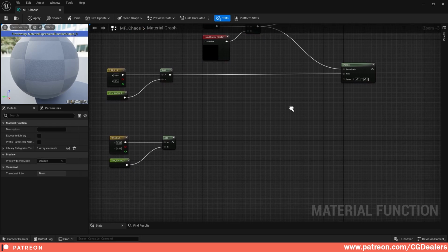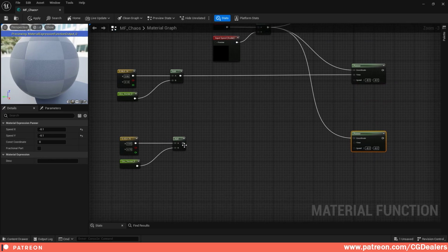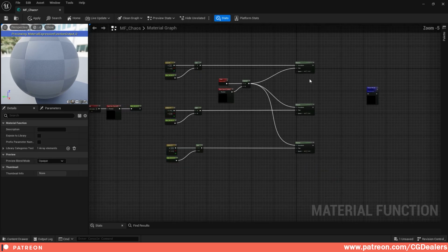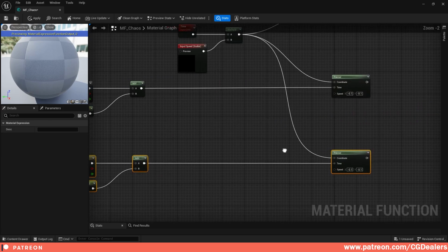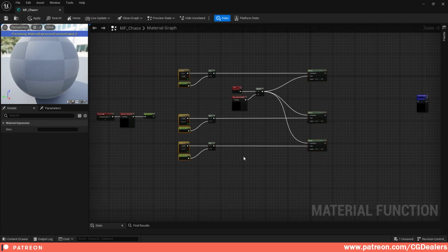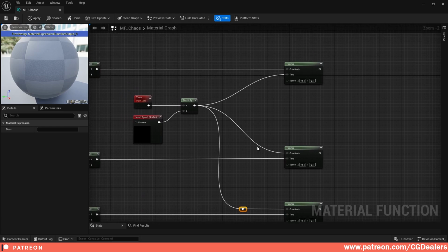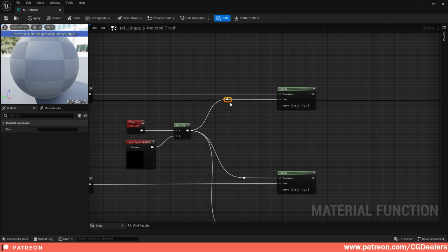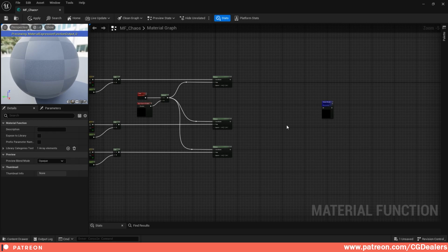And for the final one, we need to duplicate this panner again, connect my multiplication node over here, and connect the add nodes to my time. I'm going to align them too. And right now, everything is readable. You can see pretty much the connection is good. I'm just going to move this a little bit like that. Shift A, and maybe I'm going to make the connections like this, so they are more readable. And this one will have a connection like this. All right, looking good. So now we are ready with the panners and we need to move further.